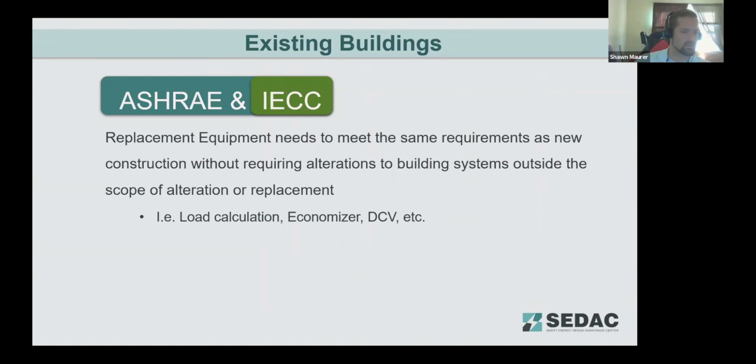Okay, looks like our poll question has got all its answers in, so we'll share those results. The correct answer is ASHRAE has more specific service water requirements for load calculations. You have to have proper sizing of that system that IECC doesn't cover, and pool covers. It's got the additional insulation, and the covers have to be on interior and exterior pools, where the IECC only requires them on exterior heated pools.